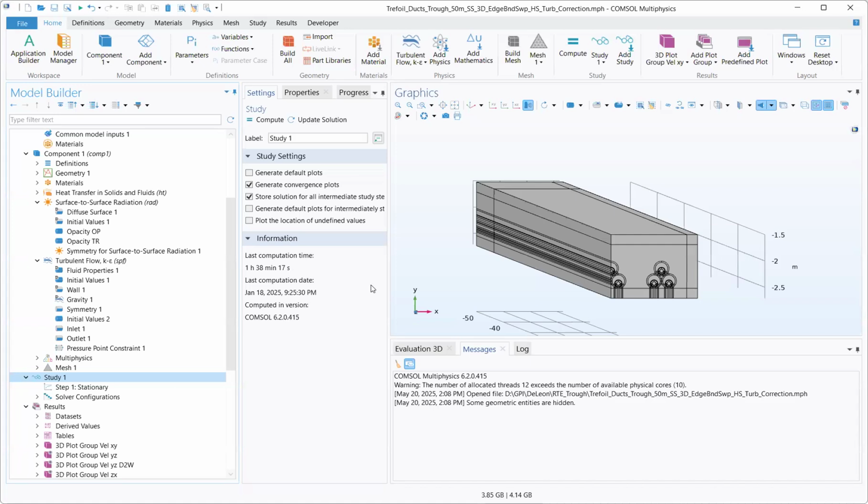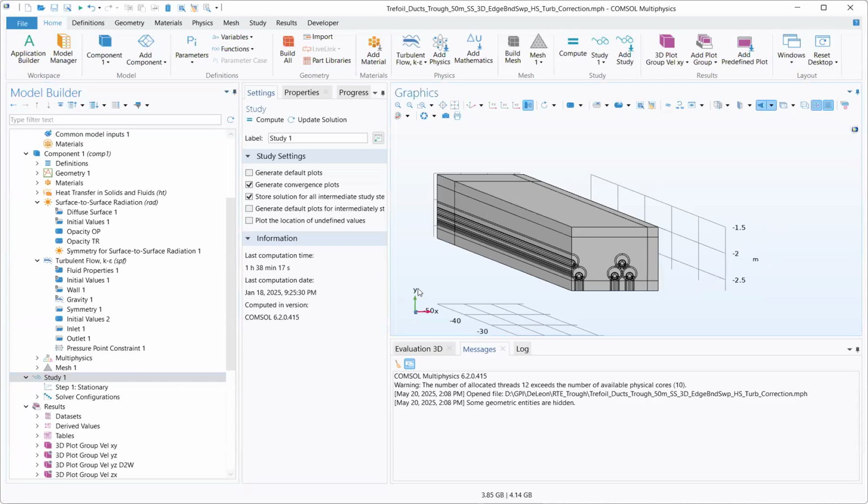But to do stationary, there's a few things you need. It's good to have an idea of what the steady state solution is going to be, right? Because we could apply a guess of what those values are, and if we guess close to the actual value, then it's going to converge easily.